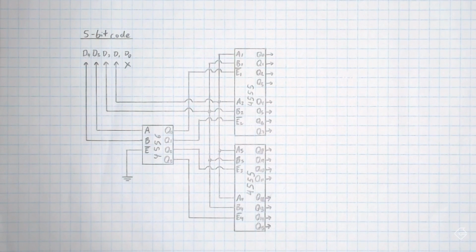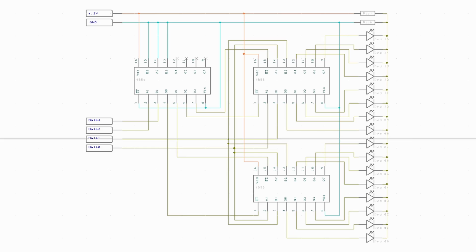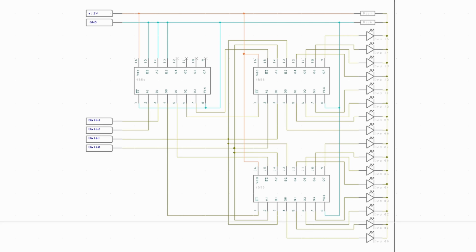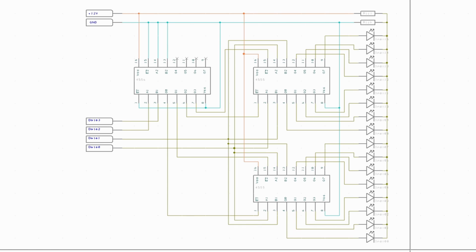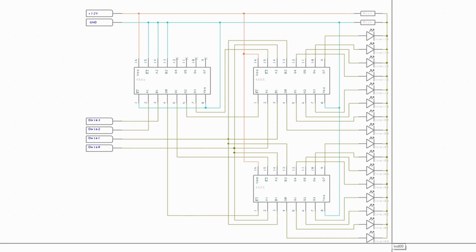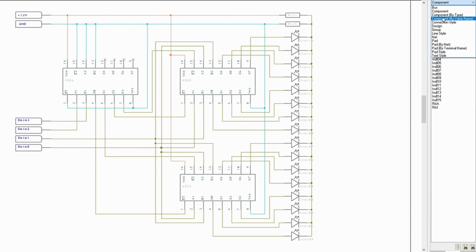So the first thing that I did is I took the original circuit from the indicator portion. I said, let me convert this to a schematic. And I did. It looks like this. There's the schematic of the indicator portion of our circuit. Now, this schematic is basically the same as the drawing. And I can do this really cool thing within this particular software: I can actually highlight the individual nets and watch them blink on my screen so I know where they're connected.